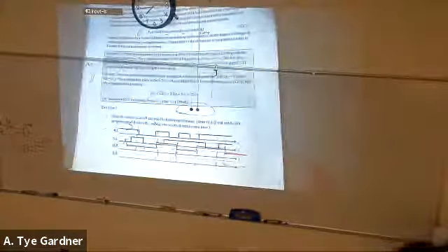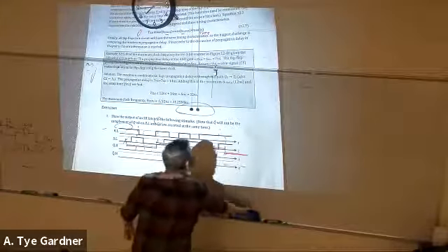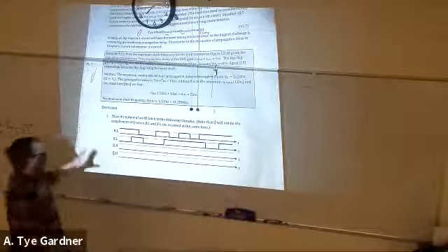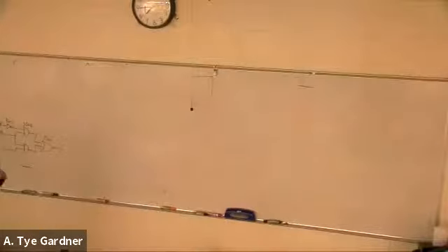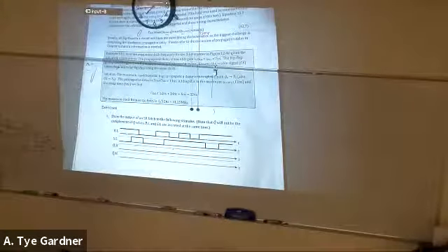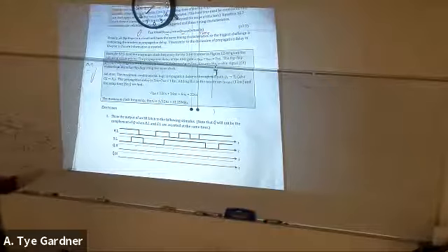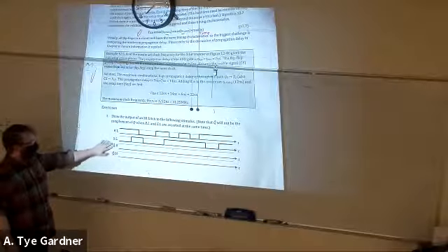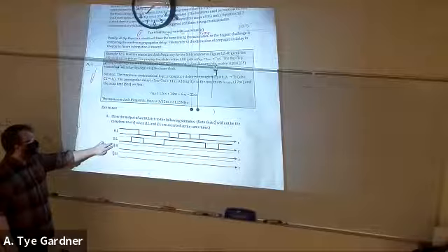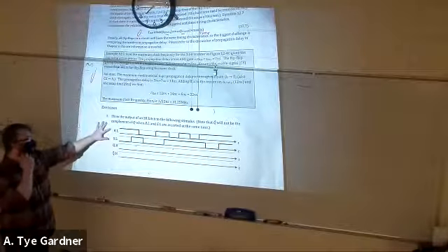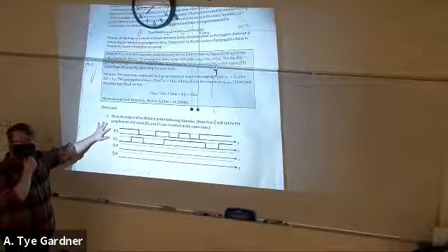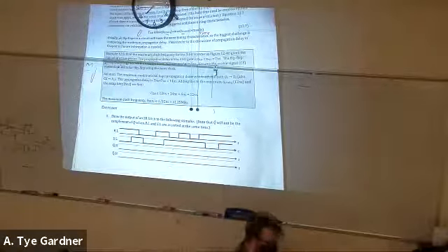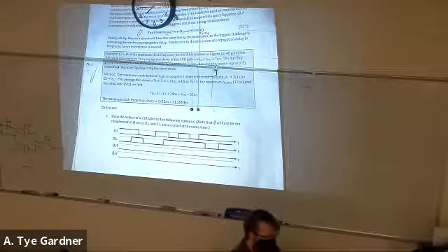So let's have you guys do this example first. This one's a little bit easier. This is an SR latch, and show how it responds to the following stimulus. Reset is active low, set is active low. Don't worry about not Q, just do Q, keeping in mind what happens when you've activated both set and reset. And I'll try and find a better example.